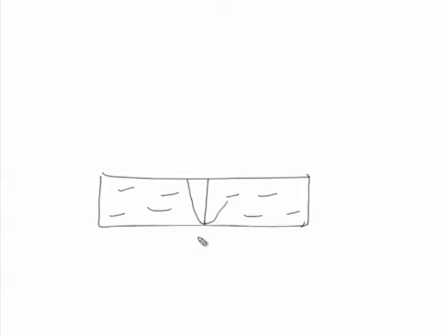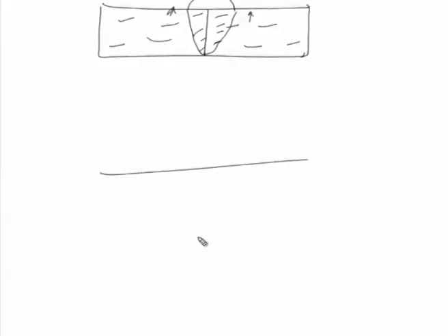To see the areas in which it mainly develops, suppose this is the base plate having inclusions in the form of laminates, and for welding, when the melting of the faying surface is done, the weld joint is developed like this, and the tensile residual stresses will be set up. When these stresses act in the direction perpendicular to these lamellars, the decohesion takes place.